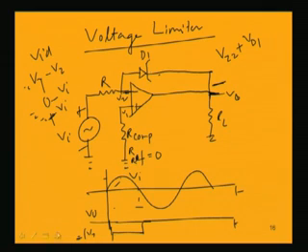So, we will be getting a normal diode voltage drop, which is 0.7 volt but negative. Then in the negative half cycle, this point is negative and this point is positive, so we are getting a positive Vsat, that is 14 volt positive.